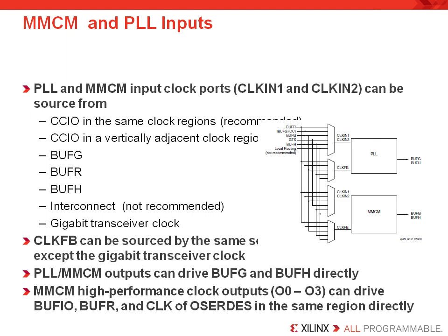A typical use of the PLL and the MMCM outputs is to drive the BUFG and the BUFH inputs for clock distribution. But outputs 0 through 3 can drive the BUFIO, the BUFR, and the SerDes clock ports in the same clock region. Clock insertion delay causes the most problems in I/O interfaces. That's because the clock to output times are increased because the clock delay path is in series with the data path. For inputs, the setup and hold time window can be extremely skewed, sometimes resulting in a negative setup time and very long positive hold time.